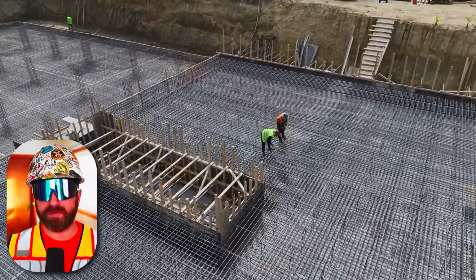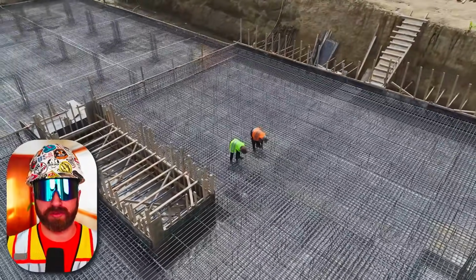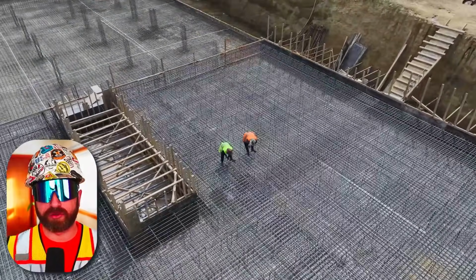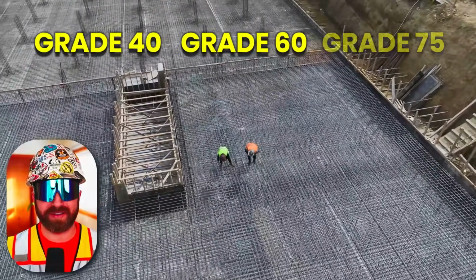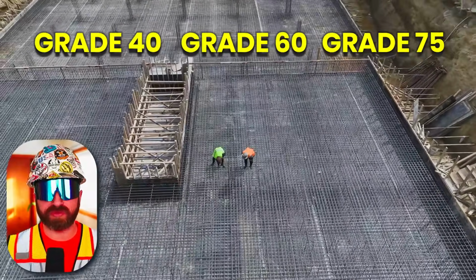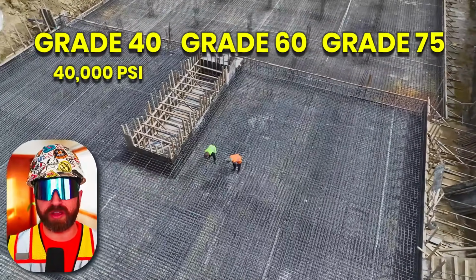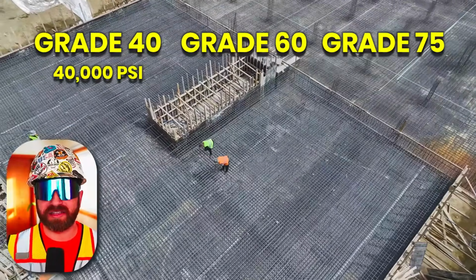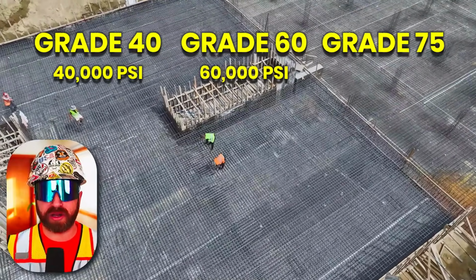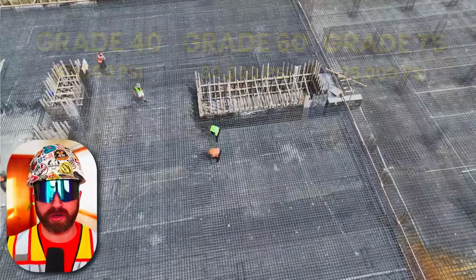Now, just a little bit more information about rebar before we get into the actual drawings. So rebar comes in a variety of grades, examples being grade 40, grade 60, and grade 75. The grade corresponds to the strength of the bar. So grade 40 yields 40,000 pounds per square inch, or PSI, 60 is 60,000 pounds per square inch, and 75 is 75,000 pounds per square inch.